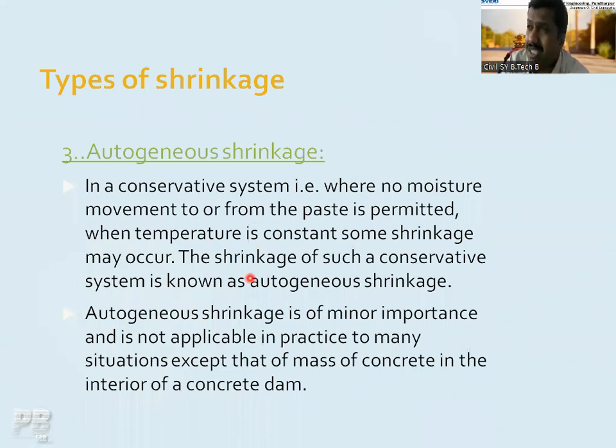Now where are you going to see such autogenous shrinkage? In the interior part of your concrete dams, the gravity dams we have, where concrete is used. So the inner portion, the interior part of your concrete. Why the interior part? If you see a concrete dam, I think everybody is aware what is the upstream side and what is the downstream side. On the upstream side, you have the water, correct? The dam or that concrete body is covered with the water only, correct?